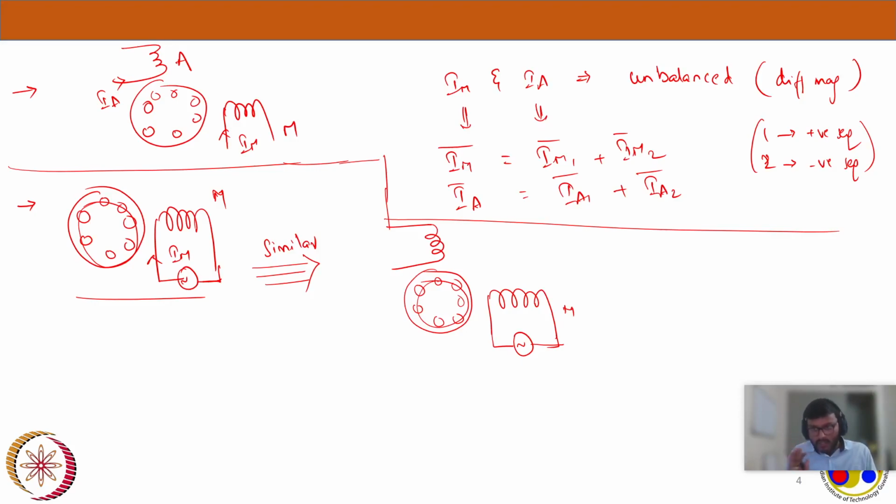I'm just making a situation where it is similar to a single phase. Now I am not supplying it with a voltage. I am not giving it voltage, and I am assuming it to be an auxiliary winding. So here my current will flow. I am assuming the current flowing through the winding is zero. Auxiliary winding current is zero. So I am exciting only my main winding.